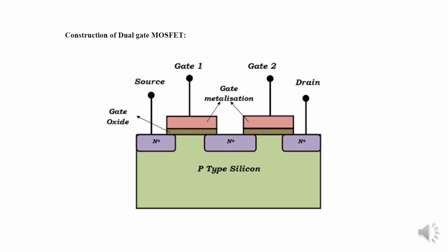and here the silicon channel is grown over a silicon oxide layer, and it is like two FETs connected in series. The highly doped N middle block acts as the drain for the first FET and the source for the second FET. The gate oxide between the gate and the channel is the dielectric layer, the metal used for the gate is a conductor, and the channel is also a conductor. So all these three layers together form a capacitor. So it is like two capacitors connected in series. The total capacitance of capacitors connected in series is lesser than the individual capacitance.